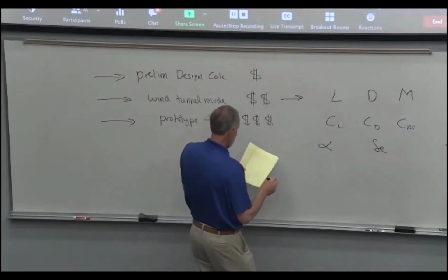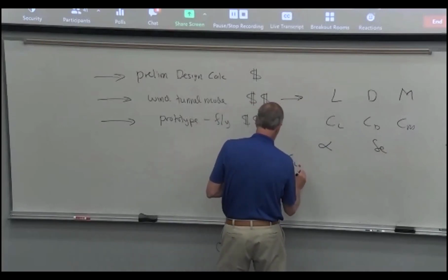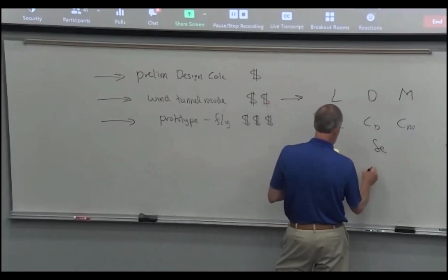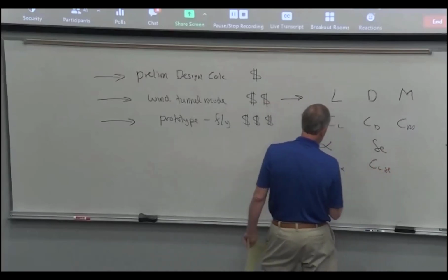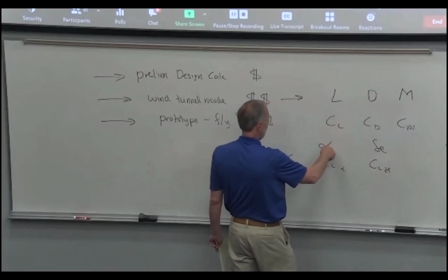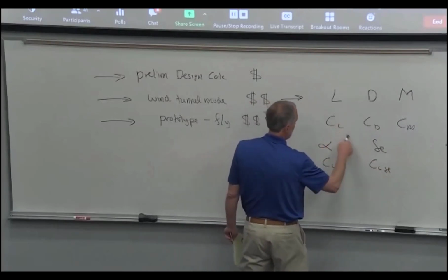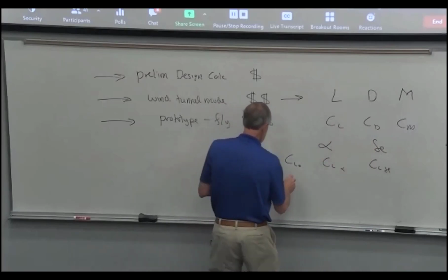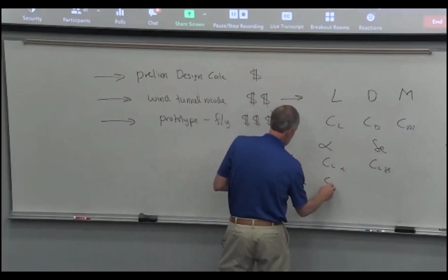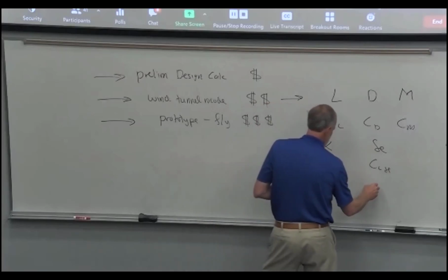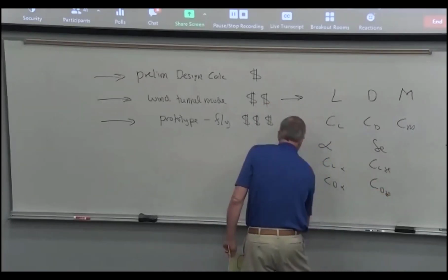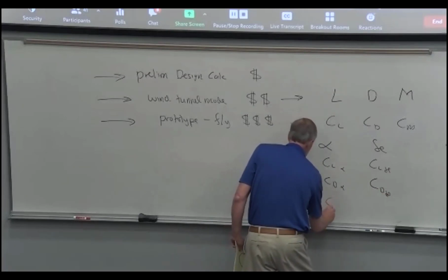And if you do that, then you get the stuff that goes into our aerodynamic models, like CL0, CL alpha, and CL delta E, because this is just the slope of the CL versus alpha plot, and this is the slope of the CL versus delta E plot. And you get that for lift, drag, and pitching moment. So these are the parameters that go into those aerodynamic models.